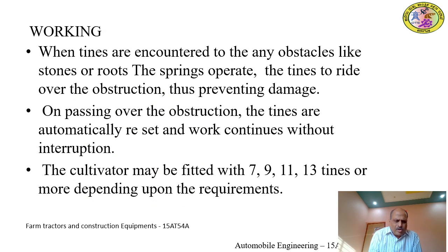Working, as we already discussed: when tines encounter any obstacles like stones or roots, the springs operate the tines to ride over those obstacles, thus preventing damage. On passing over the obstacles, the tines are automatically reset and work continues without interruption. So after overcoming that obstacle, it again fixes to its original position,